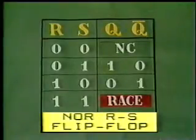Note the difference with the NAND RS flip-flop. R equal to 0 and S equal to 0 is a race condition for the NAND RS flip-flop. For the NOR, it is the no change condition. R equal to 1 and S equal to 1 is the no change condition for the NAND flip-flop, while here it is the race condition.